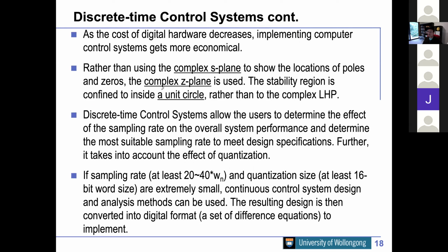That makes things quite complicated, because in continuous time you have the S domain and the Laplace transform. In digital time there is an equivalent called the Z plane, but I don't want to get into that. The Laplace transform is still quite intuitive: the left half of your S plane is where poles are stable, and the right half is unstable. With the Z transform, you go from linear coordinates to polar coordinates, things get distorted, and it becomes very much not intuitive. So we normally don't need to go that far.